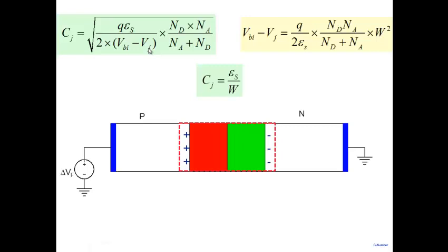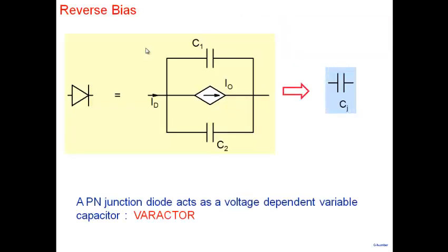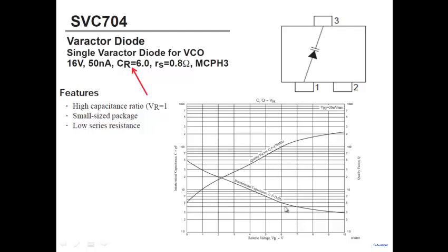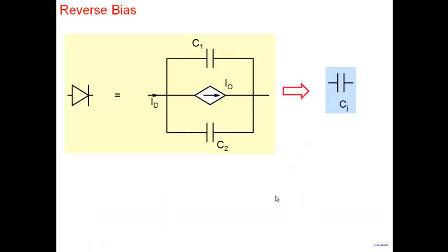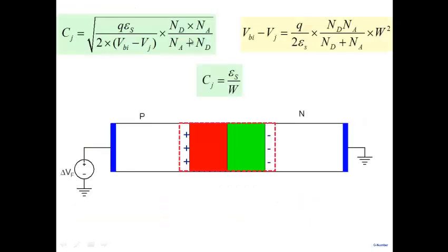Change by a factor of square root 10, which is a factor of 3, right? These guys are getting a factor of 10 change in capacitance here, which means what? It's not this kind of a diode here. Not an abrupt junction diode here.